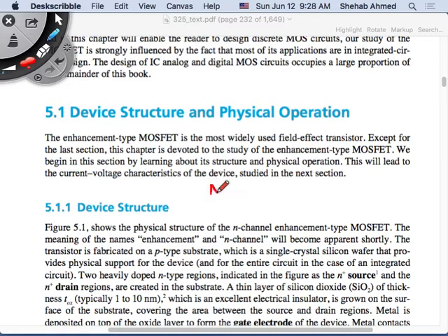There are 2 types of MOSFET: an NMOS, meaning N-channel type MOSFET, and a PMOS, a P-channel type MOSFET. These are the two types that are typically utilized. When you have both on the same silicon wafer, you have what is called, if you've heard the word before, CMOS technology. We will talk about that.